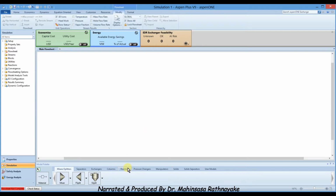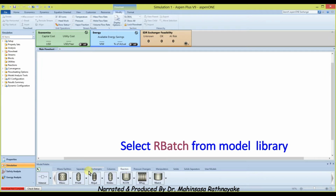Go to the Reactors tab of the model library and select RBatch block and drop it to the main flowsheet.